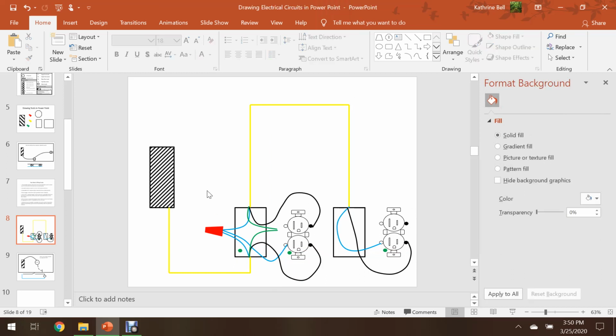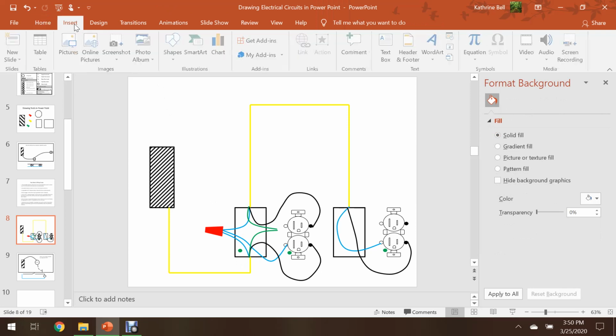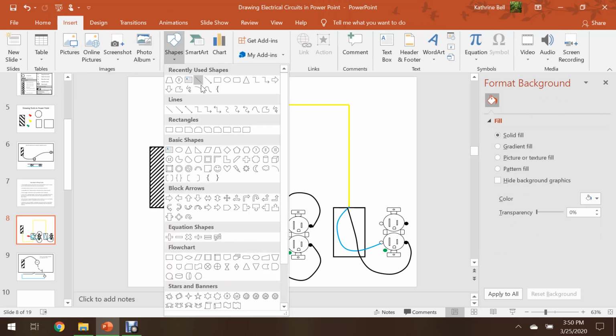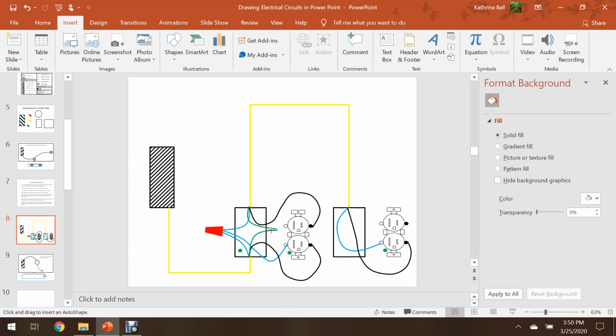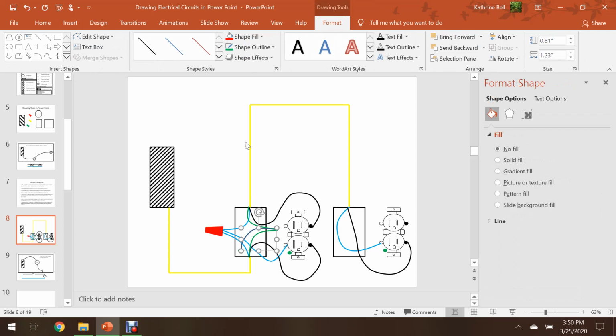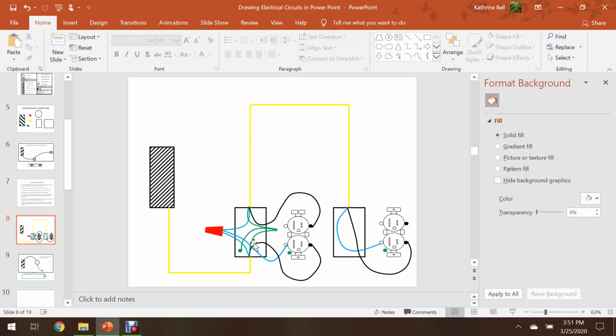Okay, then I release. We're going to connect in this box, assuming that we have a grounding pigtail with screws. So this would be a green insulated conductor that is connected to the box by a terminal screw. So in this case, my source grounding conductor, my grounding conductor leaving through non-metallic cable to my other box, and my box are all electrically connected by a bonding conductor.